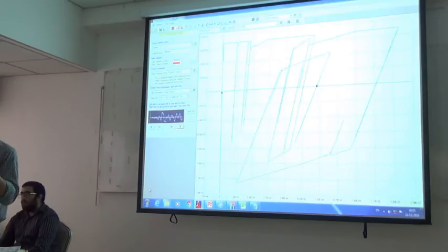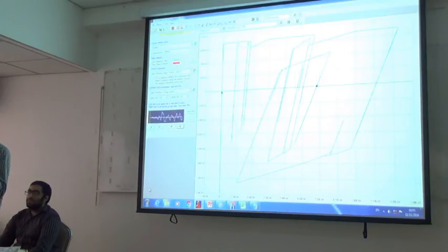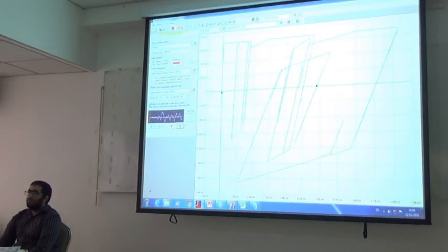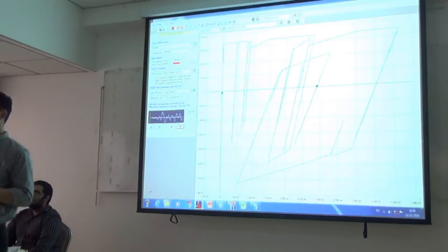Not only that, sometimes when we extract the analysis results, like the girder rotation, we have hundreds of girders, and sometimes we cannot extract the results to the text file. So in that case, we have to reduce the number of steps before we analyze the ground motions. We have a program to reduce the number of steps without spoiling the ground motion pattern. After we reduce the steps, we construct the response spectrum curve and compare the response spectrum curves before and after changing the time step. Then if they are okay, we analyze it. So normally we run about 2,000 to 6,000 time steps.